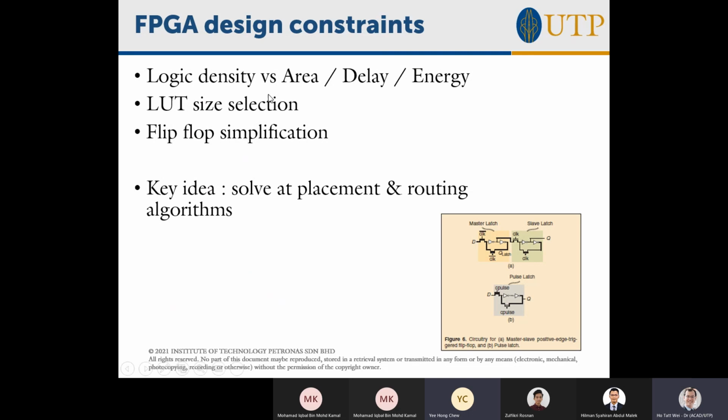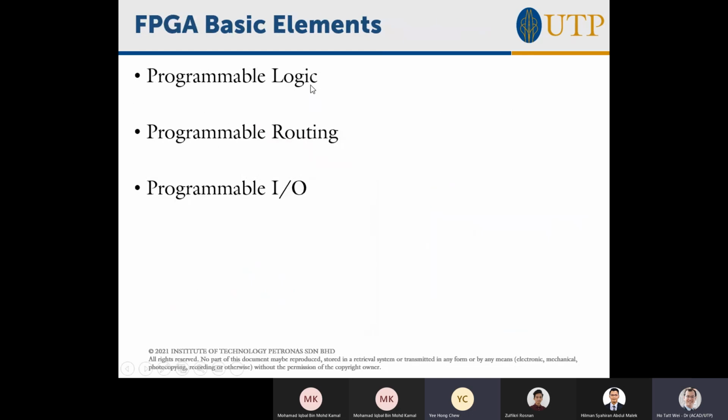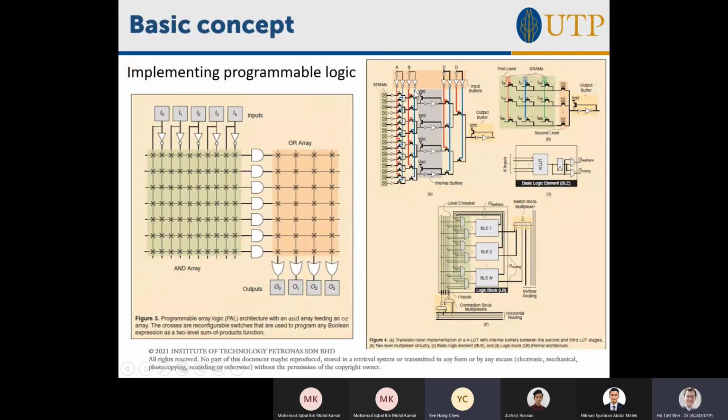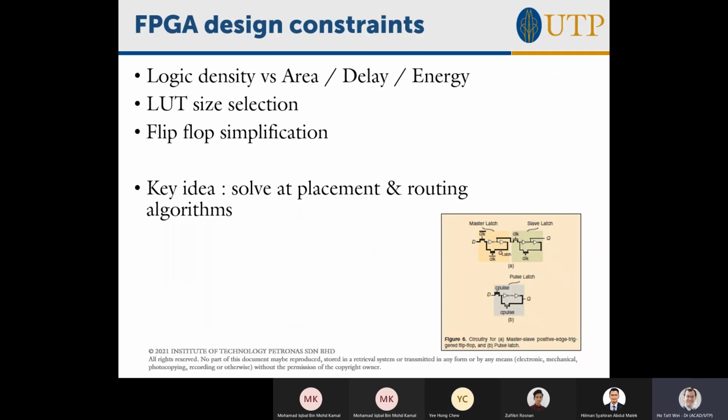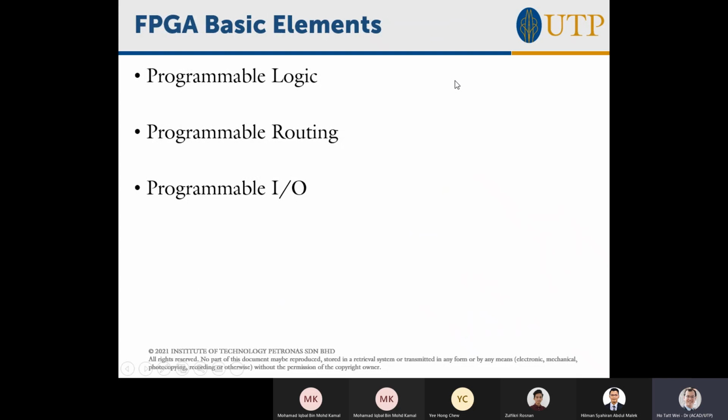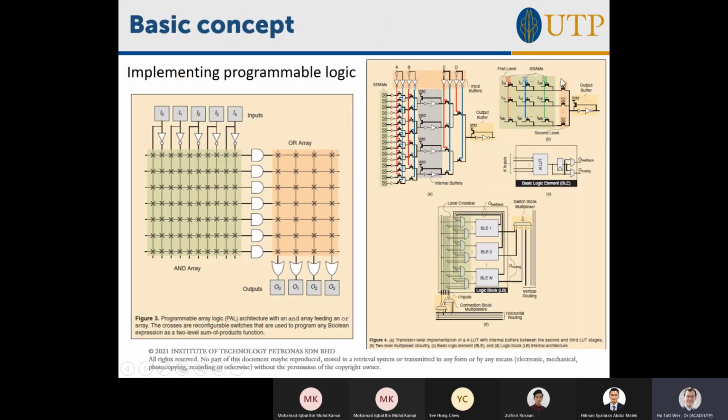And FPGA designers always struggle, because as you can see, the programmability is taking up some space. You need the SRAM, you need to be able to set certain bits to connect or not connect, and all that. So it takes a bit more area than a conventional logic gate for an ASIC. That's one disadvantage of FPGAs. And in the earlier days, the delay was higher and it consumed more energy, because you've got all this additional programmable infrastructure to allow you to program it.